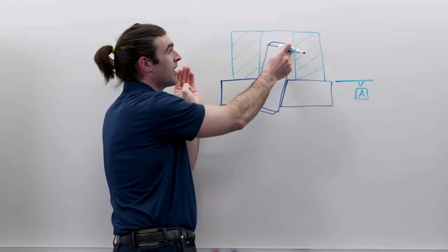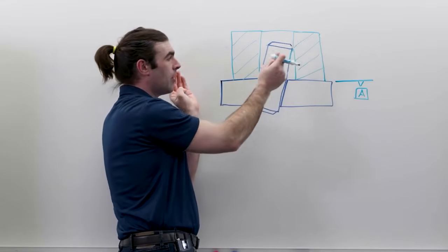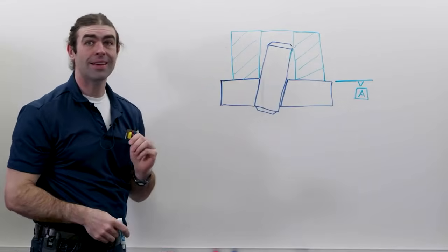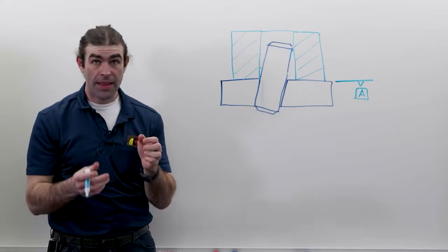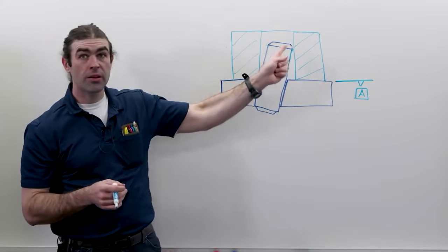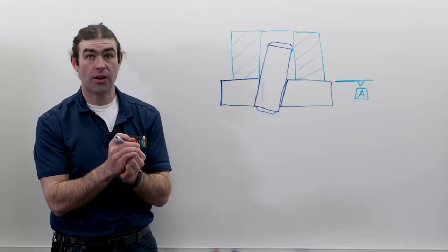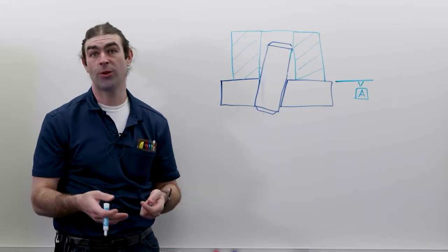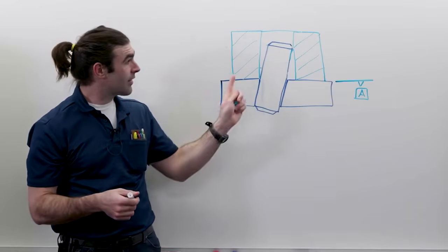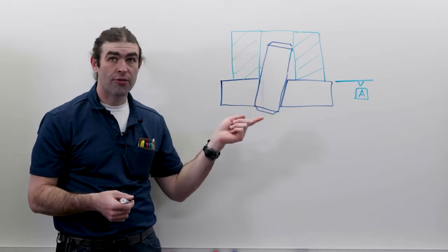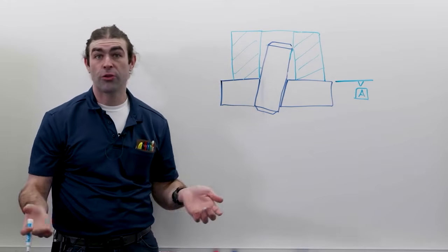Eventually, it's going to touch one point of the pin here and one point of the pin here. Now, that opening is going to be larger than if you just collapsed it on the pin, because now it's taking into account a datum. This is the related actual mating envelope, which also is usually the virtual condition.